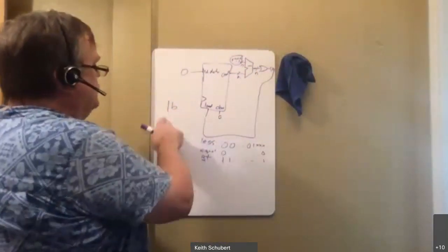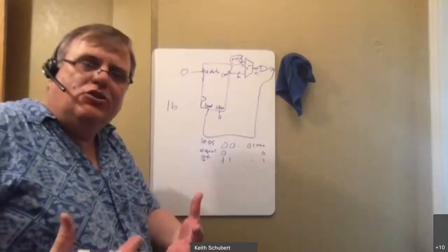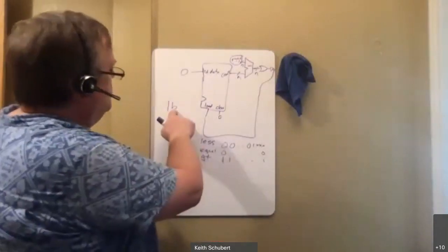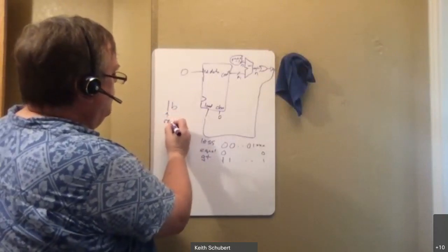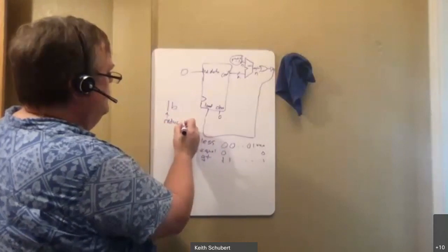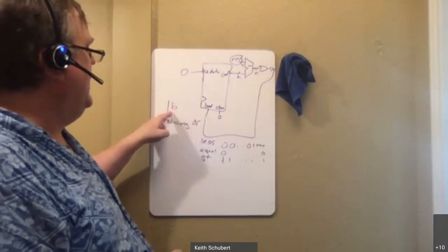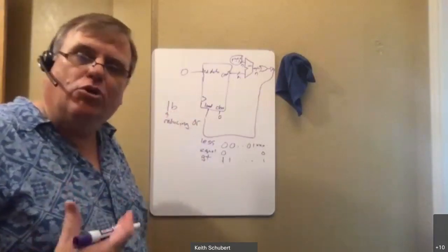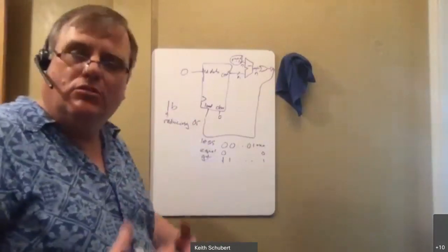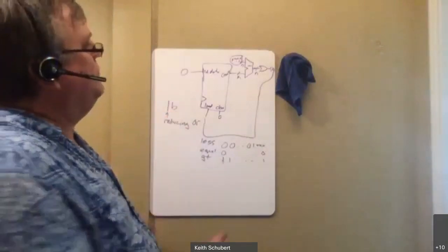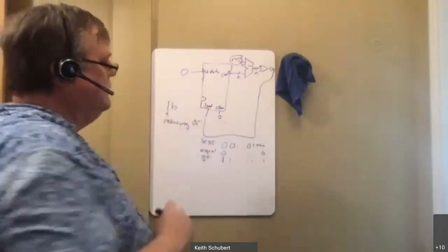There's a slightly different version where I just say |B, right? That technically should be illegal logically, but if B has multiple bits, this has a special meaning. This is then called a reducing OR. And what that means is take all the bits of B and OR them together. So it's a shorthand notation for us. It just says, hey, this is a quick way you can reduce it down to get a single value out of it. And that's what we're doing here. So this is a very easy operation inside of Verilog.